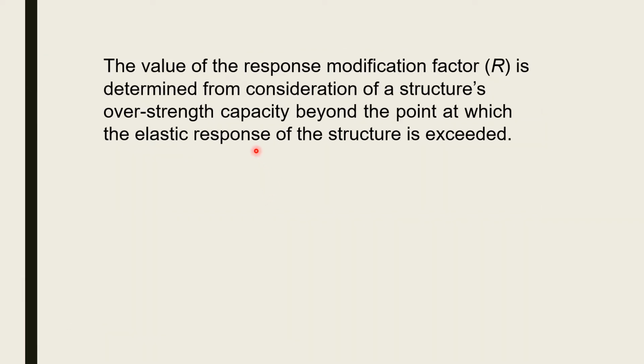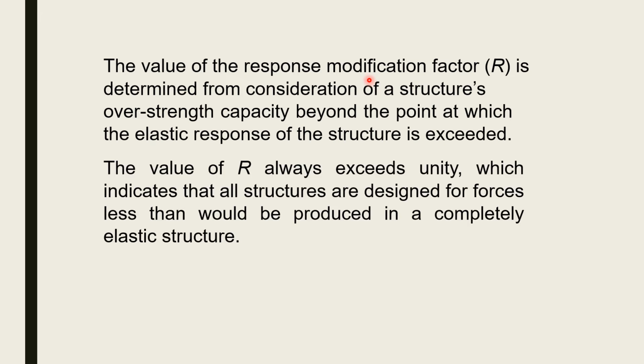Next, the value of the response modification factor is determined from the consideration of the structure's overstrength capacity beyond the point at which the elastic response of the structure is exceeded. This means that the major part of the response modification factor depends upon the strength or overstrength limit beyond the elastic range. Means, in the inelastic range, it is more dependent upon the response modification factor.